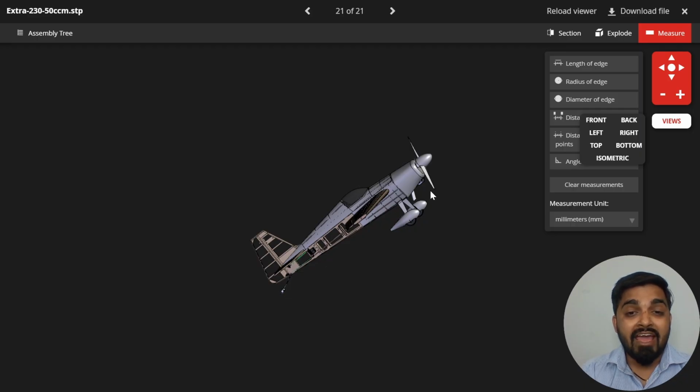When the angle of attack exceeds the critical angle of attack, which is roughly 15 to 18 degrees, the smooth airflow over the wings breaks apart and becomes chaotic and turbulent. And finally, the wing stops generating lift. So in this scenario, very terrible things can happen.